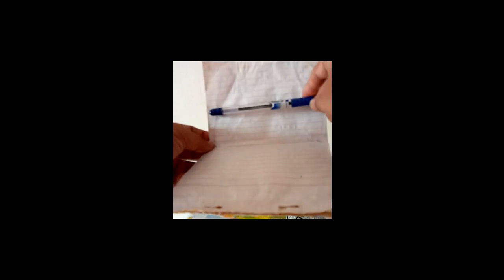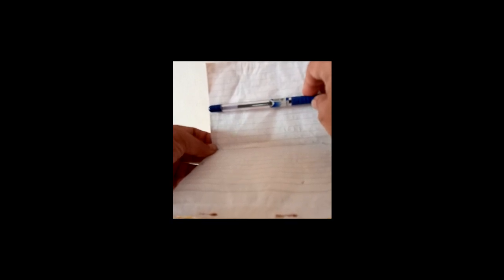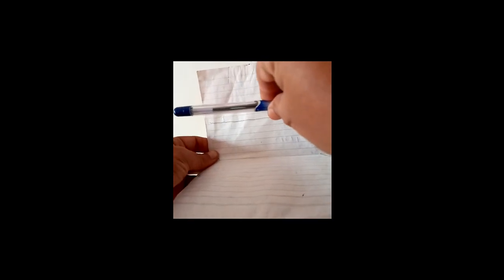So if you locate a point, we will try to draw the front view and top view of the line. The front view of the line means the projection of this line onto this VP, the vertical plane. This is the front view. So replacing that pen, I am drawing the line. See, this line. And actually the top view means the same line, the projection of the line onto the horizontal plane. I am drawing a line there.